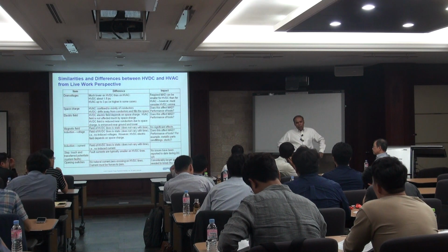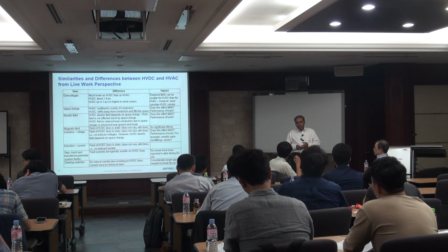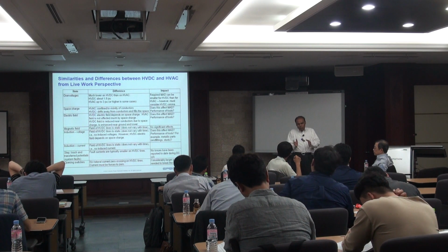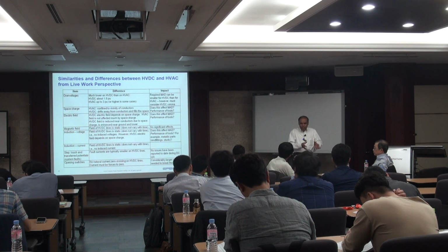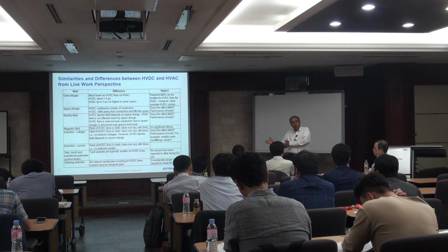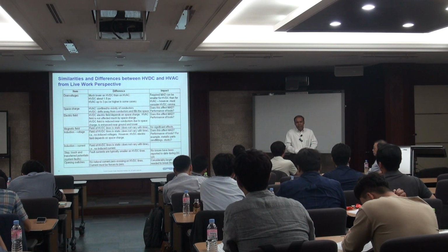Yeah, sure. Suppose it's raining now. Take an AC line, you have more corona, and suddenly it becomes sunny, that will reduce. The AC corona will be reduced. Whereas if you take DC lines, if it is raining, less corona, and it becomes sunny, you will have more corona with the DC lines. It's just exactly opposite, AC and DC.